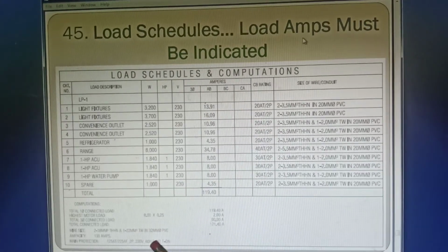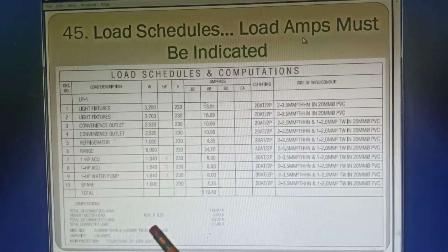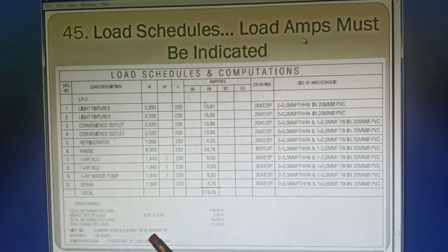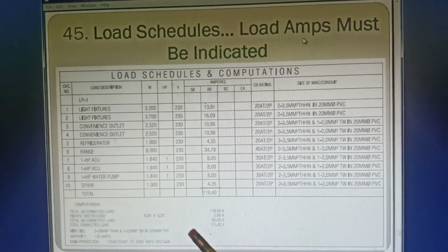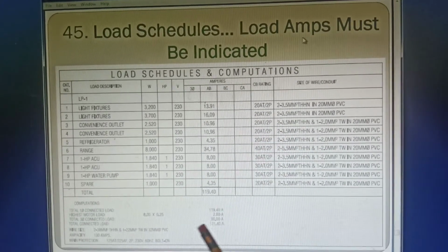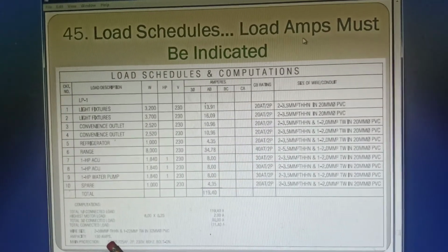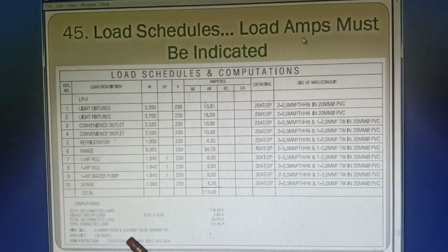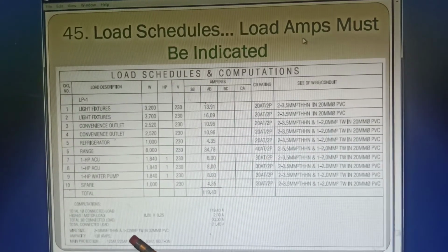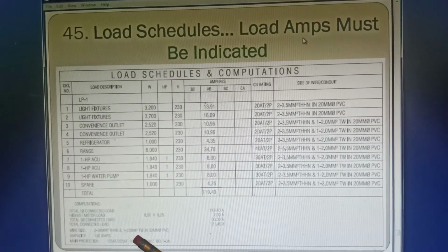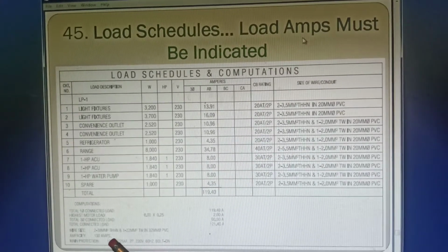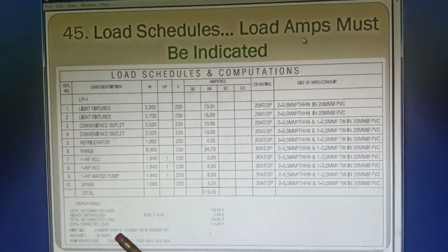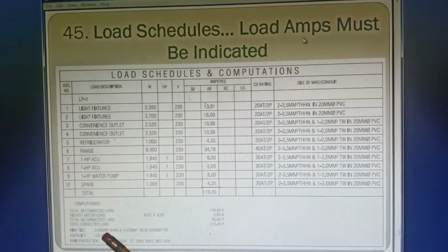And then of course if you want to make your service entrance fully have the capacity, you can just use this total as the basis of sizing the service entrance wire. So in this case 38 mm² THN is selected, and 22 mm² is the size of the ground wire. Okay, and the circuit breaker must be selected exactly to protect the selected service entrance wire.